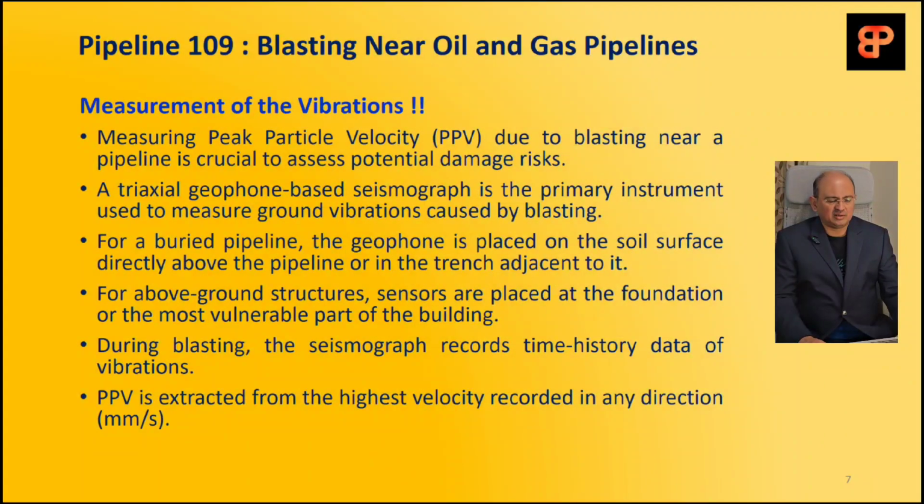Measurement of these vibrations or PPV due to blasting near the pipeline is crucial, as I mentioned before, to assess the potential damage risk involved. A triaxial geophone based seismograph is the primary instrument used to measure ground vibrations caused by the blasting.